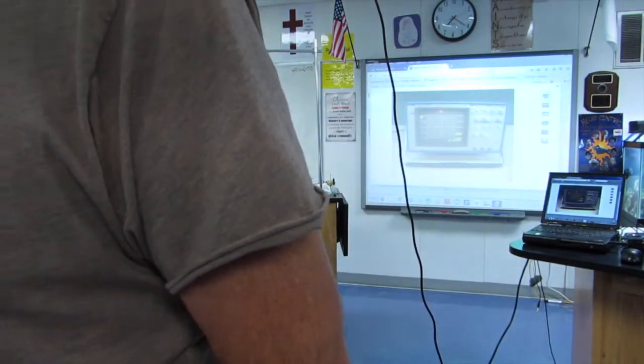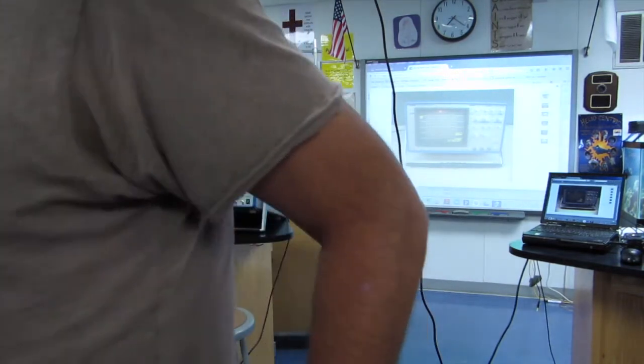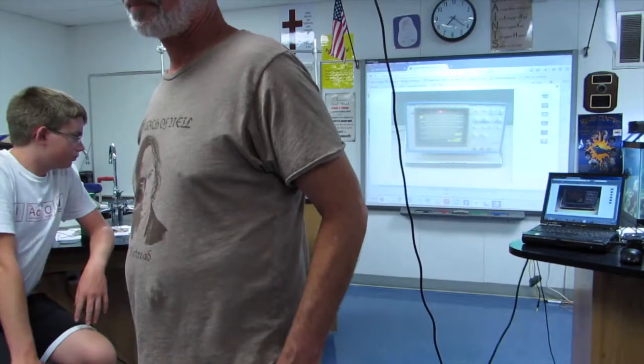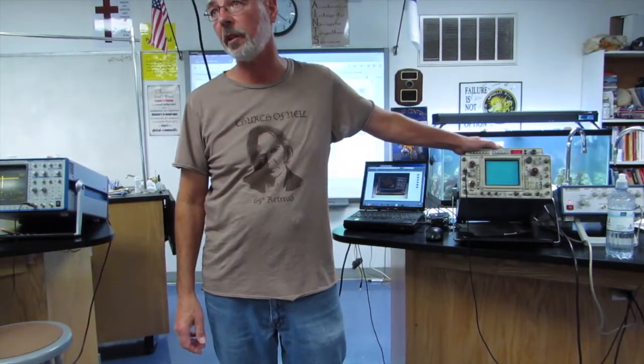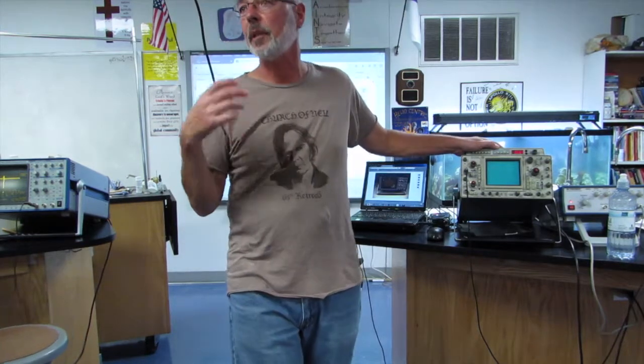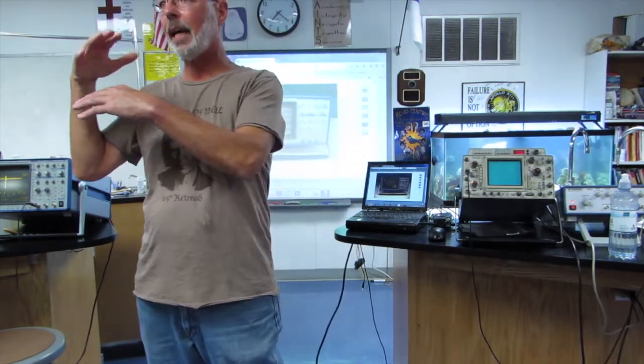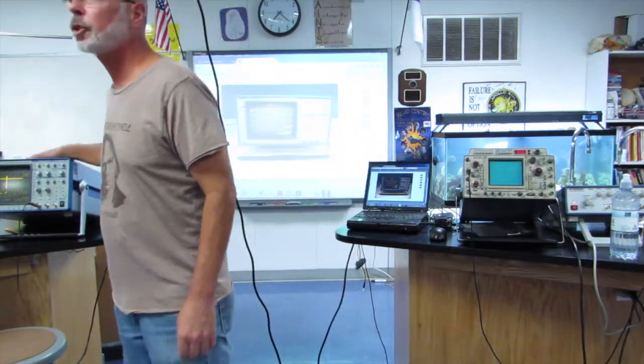I have a question. What's the maximum resolution, if you will? What's the maximum polling rate that it will measure? Right, that's known as the bandwidth of the scope. This scope has a 350 megahertz bandwidth, which means that if you put a 350 megahertz sine wave into it, the amplitude will be reduced by 3 dB. That's the roll-off point. So you will accurately see a 200 megahertz waveform, for example. Anything above that will start shrinking in amplitude toward zero. It rolls off.